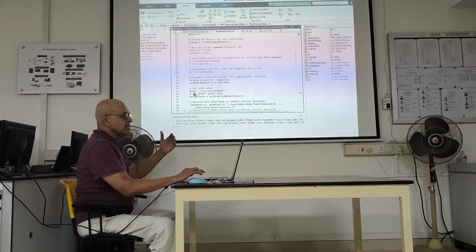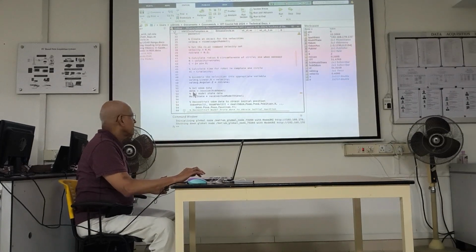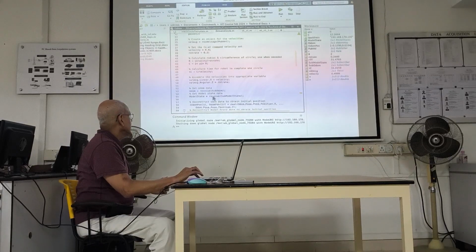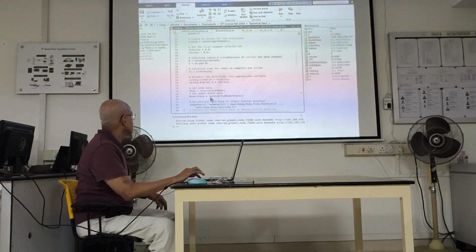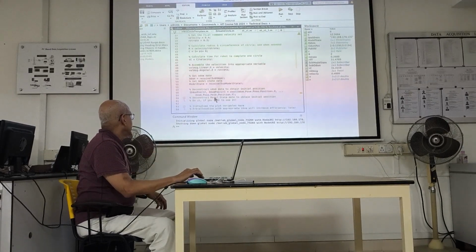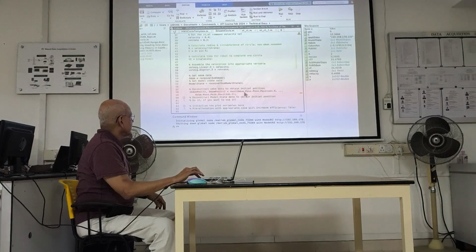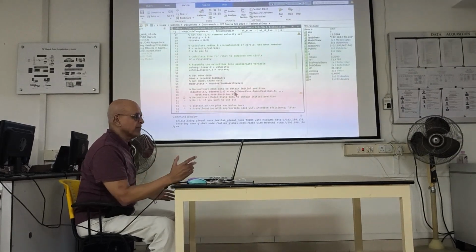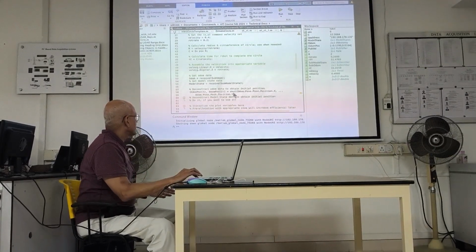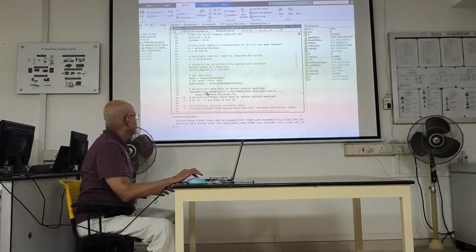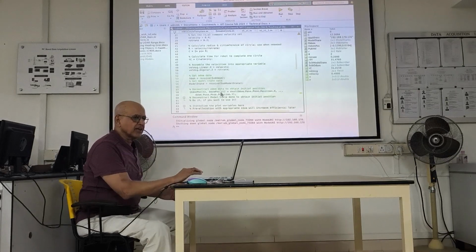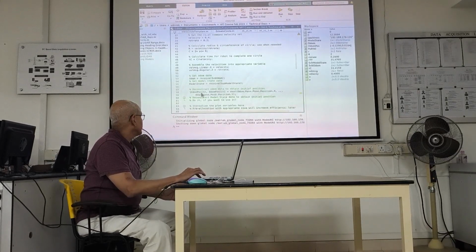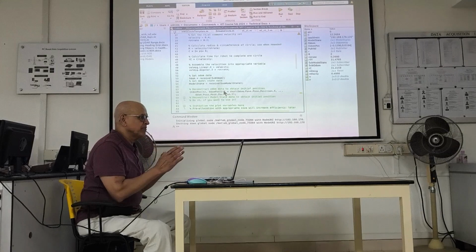Now this is the other part, getting data in from the odometry. So receive sub-odom. You don't have to worry about model state. If you want to, you can try it and compare it with the odom results. And then I told you, I prefer not using these long variable names, so I unpack it and put it into odom pose 1 and odom pose 2. You can call it X and Y if you like, but odom pose 1, odom pose 2 is the same array.